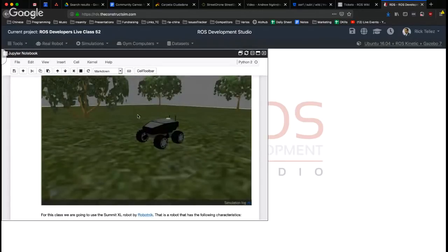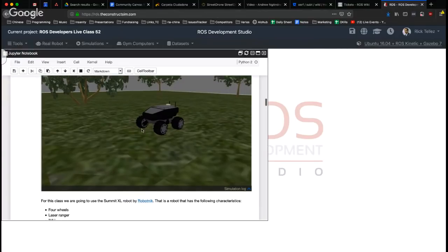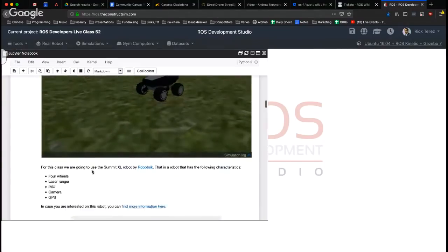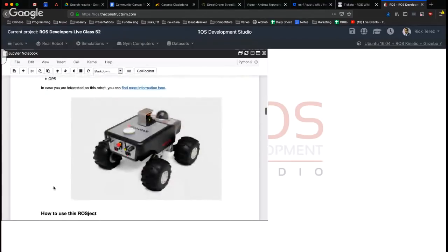If there are other people, the robot can get confused very easily because there are almost no features there. So for that, let's use the GPS, because we are outdoors and the GPS signals are there. This robot already contains a GPS. It also contains a laser, of course, and a camera and IMU. So let's use all that.